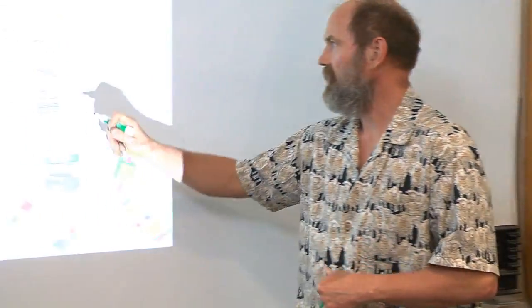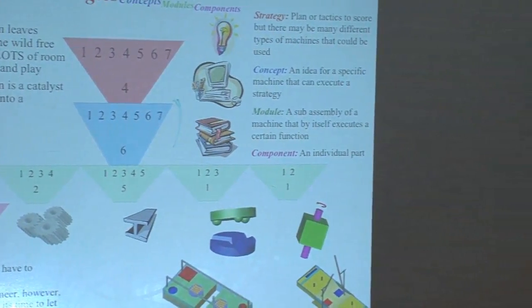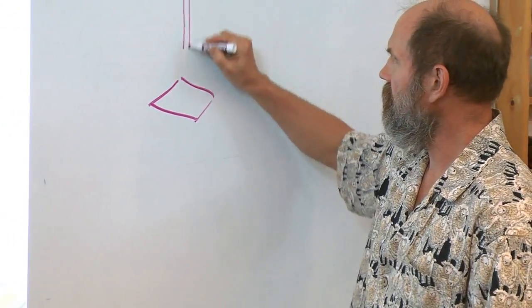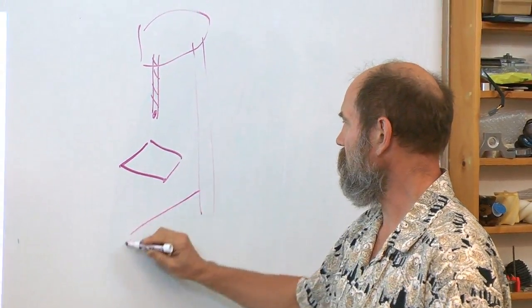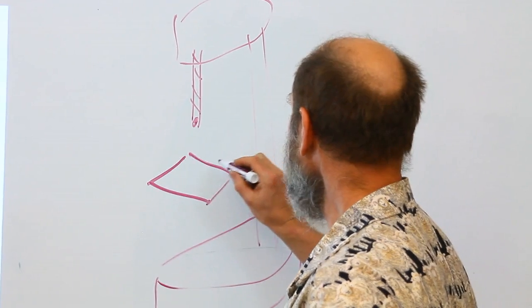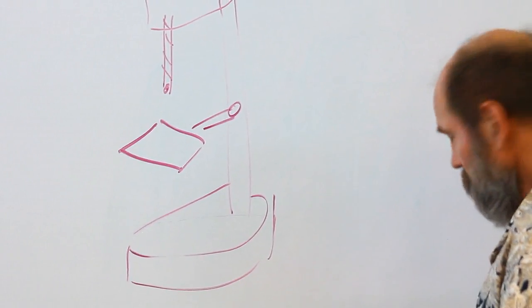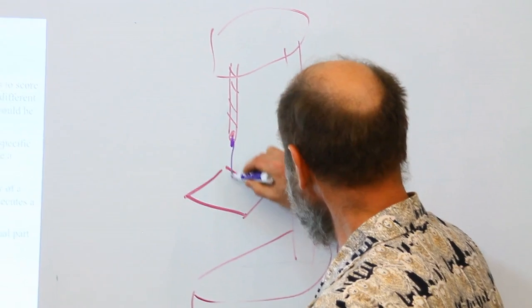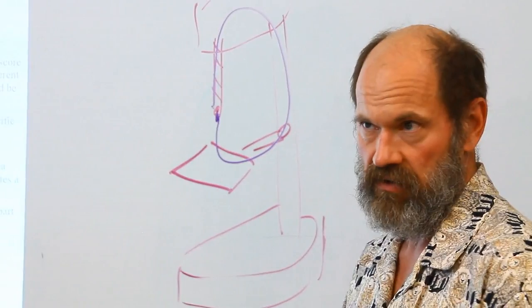And what are different concepts for that, how to do the table? You can start with the idea of part, drill, and notice what I'm doing here, I'm sketching real fast, and we'll get a lot more into this in topic 2 about some of these techniques. And in future topics, we'll talk about things like what's called the structural loop. So these are things why it can be good to read ahead. Structural loop being the flow of forces through the machine, just like in circuits, the flow of current through a circuit.